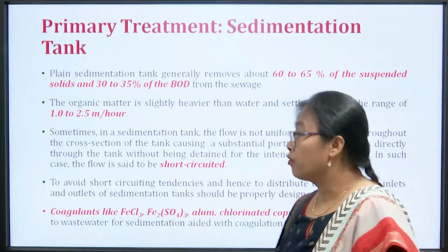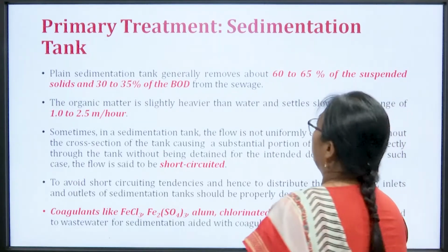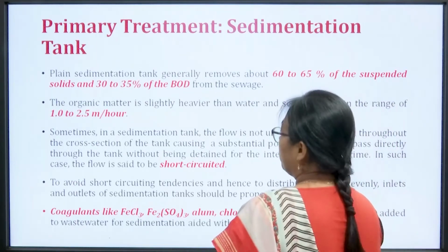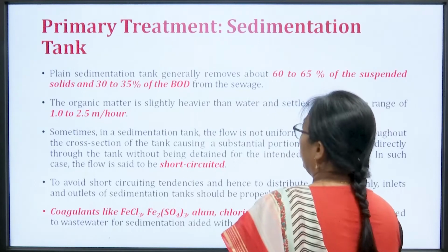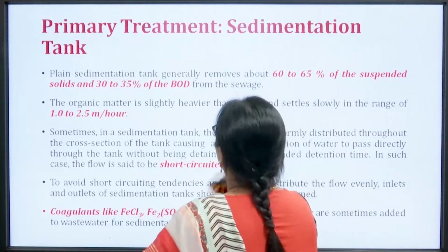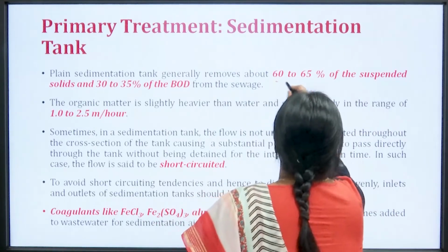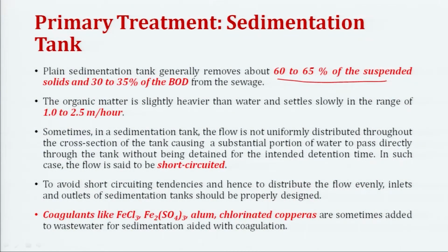Coming back to the sedimentation tank, as I have already told, in a plain sedimentation tank we generally remove around 60 to 65% of the suspended solids and 30 to 35% of the BOD.